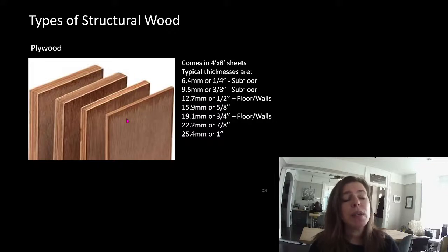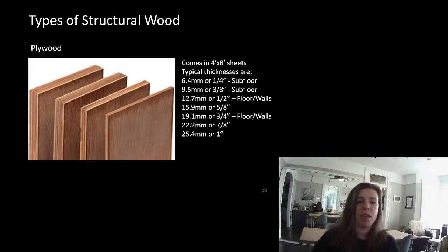Plywood is like our deck. Remember our metal deck? Plywood does a similar job. It's the surface that fills in all of the bits. It comes in 4x8 sheets, but it doesn't span 4 feet or 8 feet. It needs something in between to support it.